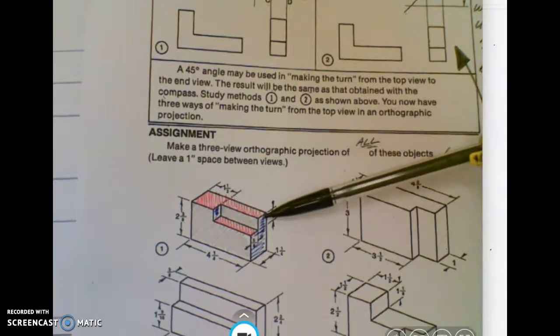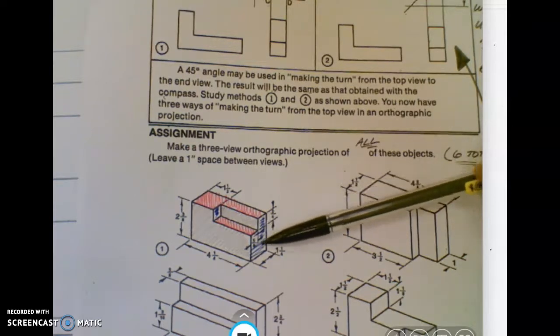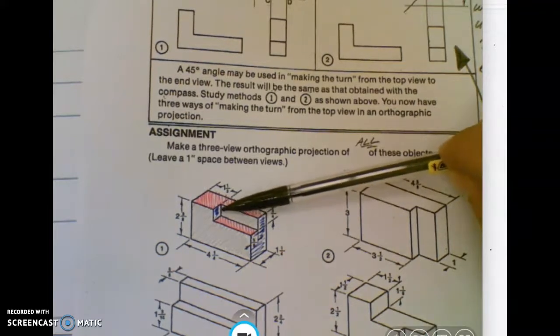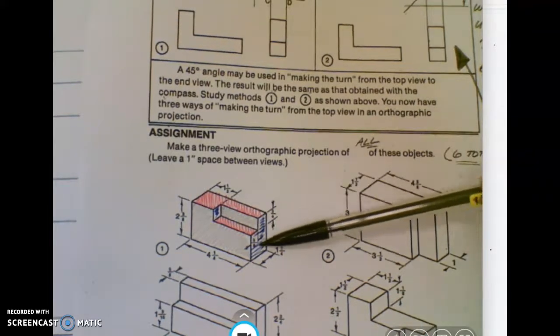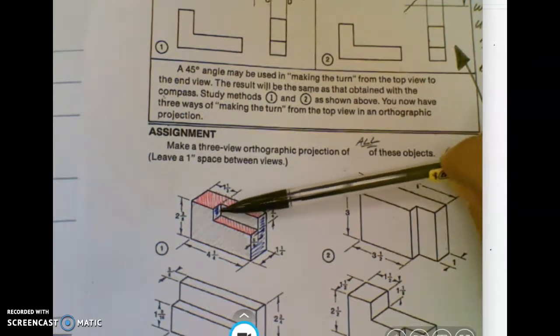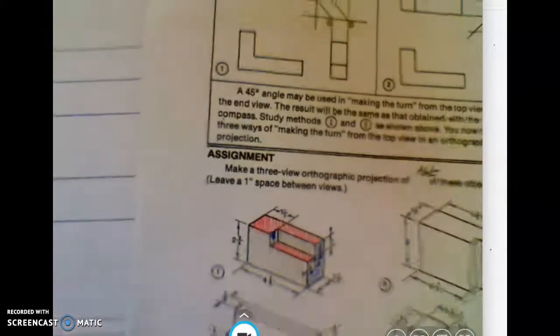I've now shaded in the side view in blue. So I'm going to have another L shape. The L shape seems to be a common theme here today. And then a small square in that upper left-hand corner. So the L shape is my near plane, and this square is in my far plane. Now again though, it doesn't stick out. They're always contained in a rectangle. Hence why it's important to use your construction lines and block in where those views go.